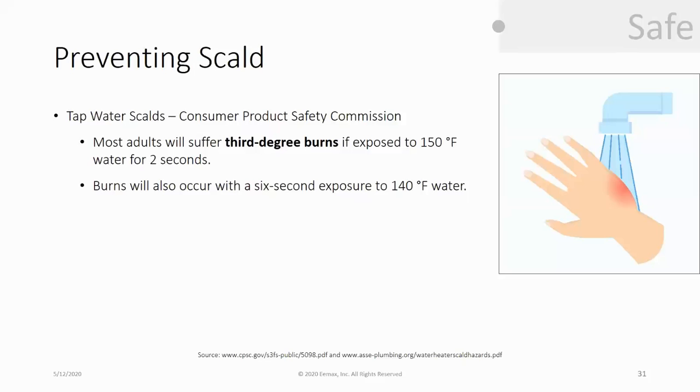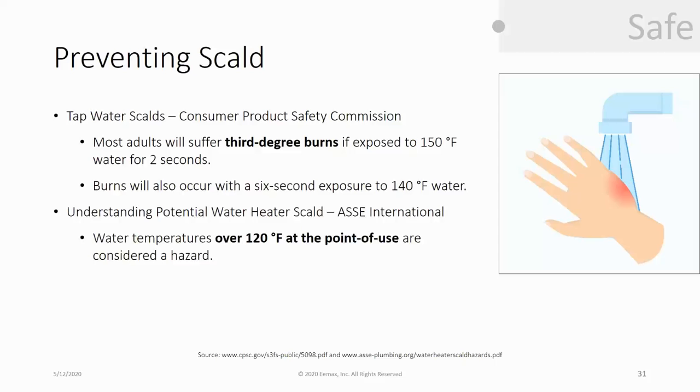So the main thing is to prevent scalding. 3rd degree burns if exposed to 150 degrees for 2 seconds. 6 seconds of 140 degrees will give you 3rd degree burns. Understanding the scald is one of the key goals of ASSE, and they state any temperature above 120 at the point of use is a hazard.